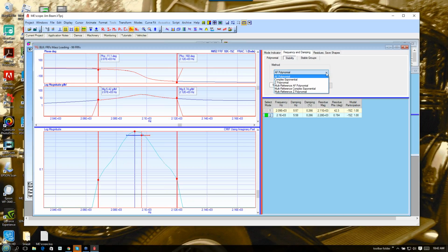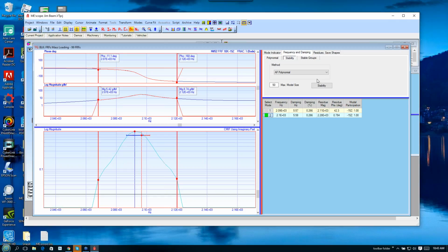So I can steer around all those issues by using the polynomial fitter in small bands. And again, I can use scripting. If we have time, Mark, I can show another example where I use scripting to go through and curve fit a number of bands of data. I've even got some bad data so that with the scripting I can tell it where to curve fit and come up with some usable mode shapes.